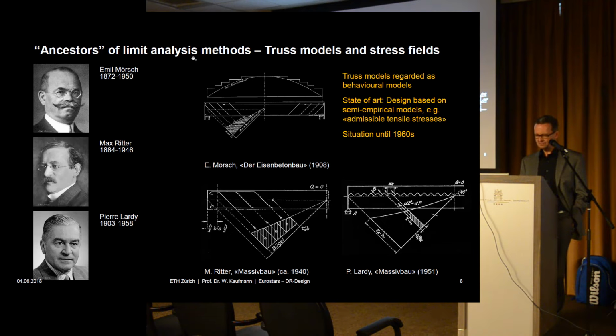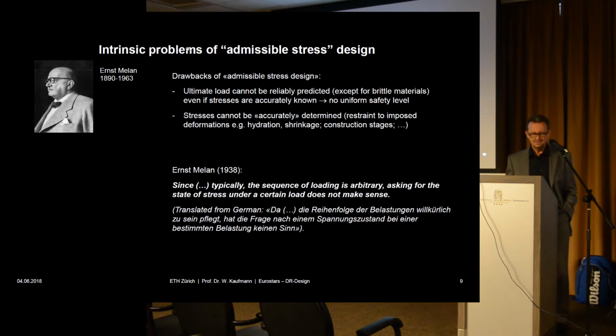And people became aware with time that, of course, calculating stresses based on the theory of elasticity is not the truth either. Because you have construction stages, you have restraints, in steel structures you have welding-induced stresses. So you cannot calculate the stress in a structure.